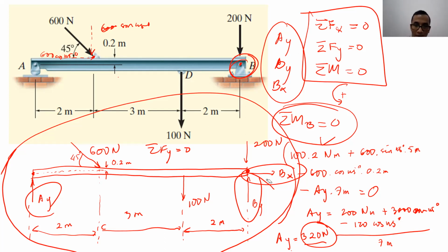On the other hand, when we take a look at A, it's a roller joint. When you give a horizontal force at the roller joint, it will slide, right, Aurelia? Yes. So there is no restriction in the horizontal force. Because of that, there will be no AX there.